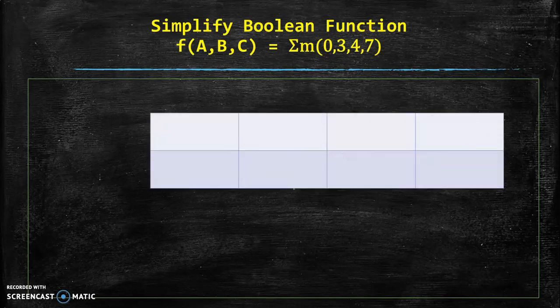Now let us first prepare our usual K-map. We write variables AB and we give numbers to each cell, that is 00, 01, 11, 10. This you should notice and you should always remember how and why we are writing this. Then we have variable C, and we write numbers for the cells, that is 0 and 1.